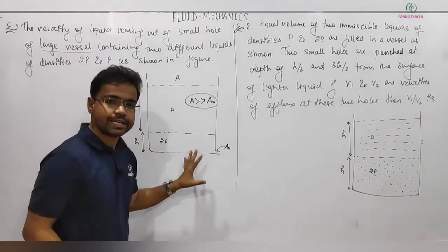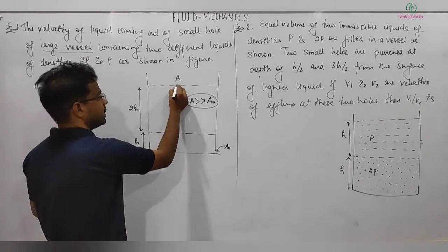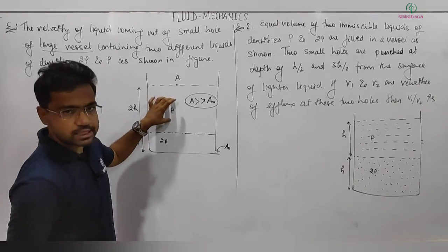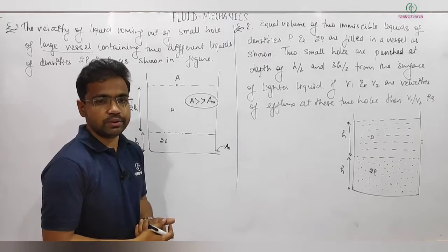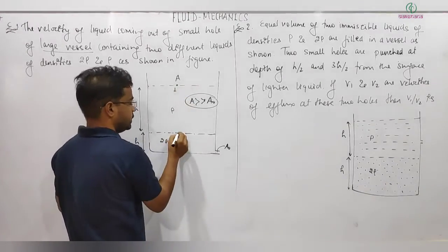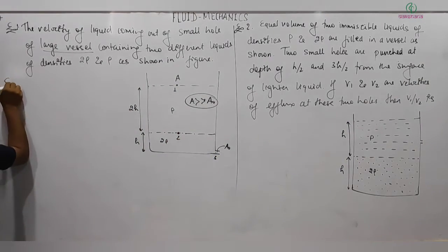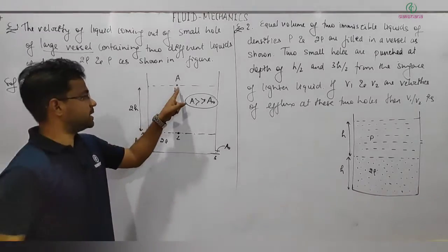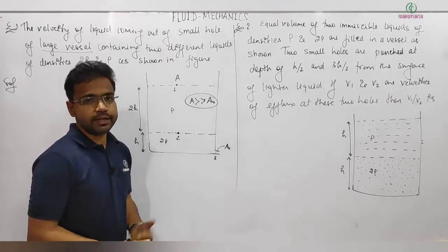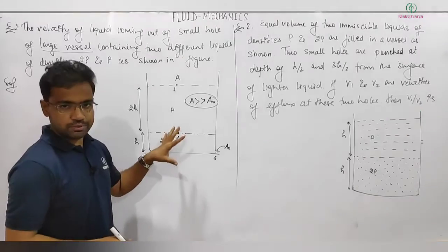So how do we deal with this case? There is one simple method. You just need to learn that. We can basically apply Bernoulli's principle between these 2 points, and we need to take care that density is different, so either way you can go. Let me mark, this is point 1, this is point 2 and this is point 3. So we can go in two ways, by applying Bernoulli's principle directly between point 1 and 3, or between point 2 and 3. Either way, these are just different methods of calculation. Learn both the ways. Let me tell you.